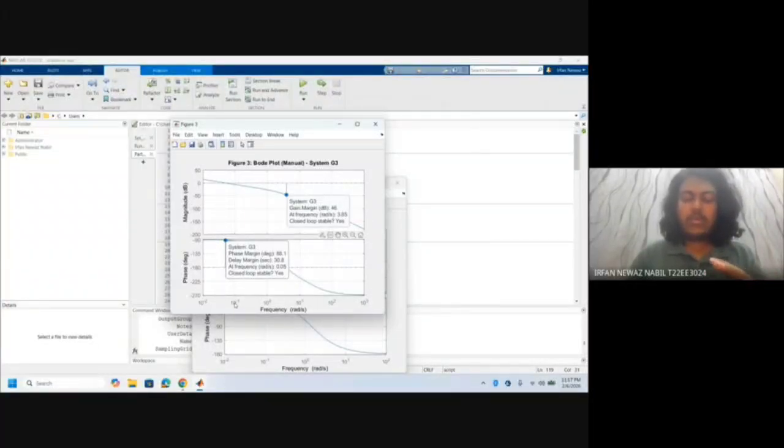From systems G1 and G3, we can interpret that the zero improves stability and phase margin, making G3 more robust than G1. Like G1, it is type 1 as well, so zero steady state error to step input, and finite velocity error constant Kv. These demonstrate how zeros can be used to shape the frequency response and improve robustness.